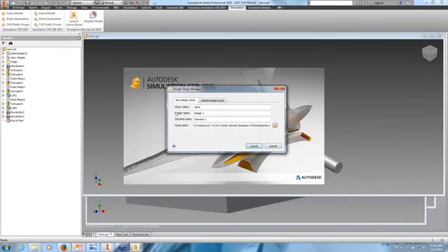So you can see we have study, design, and scenario. The study is basically the overall file name. Under that one file name, you can have multiple designs, and under each design, you can have multiple scenarios. The difference between one design and the other would be a different geometry. So you can model, what if I change the geometry? What's going to happen? Under each design, you can have different scenarios where you can change the boundary conditions.